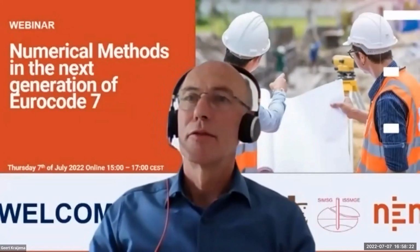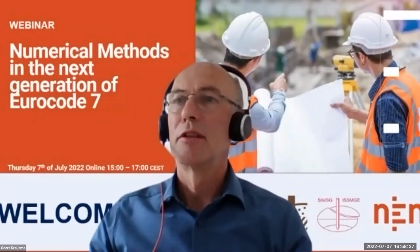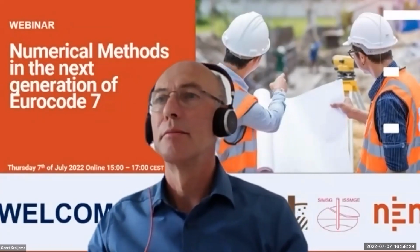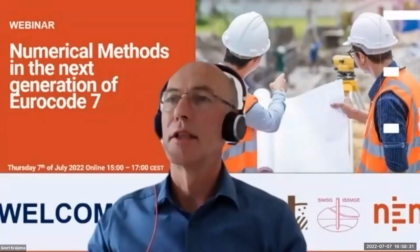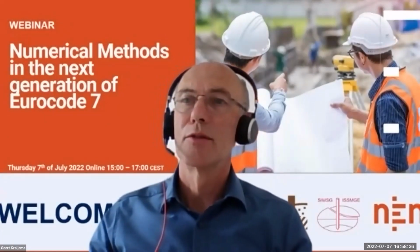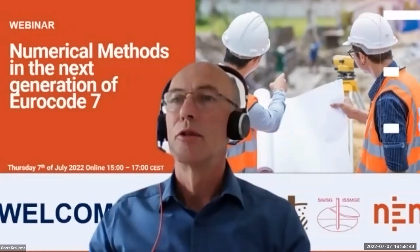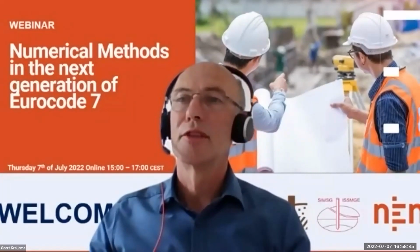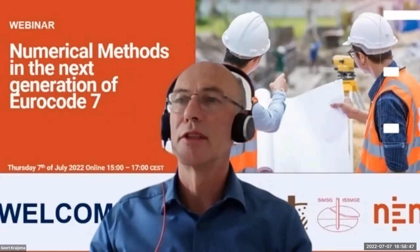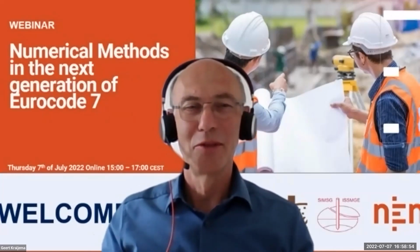So the next question is from Darius. Do you know whether the required minimum values of the reliability index beta as per EN 1990 are reached using the new numerical modeling methods? The numerical methods potentially allow lowering the model error. Therefore, perhaps the material factors could be reduced to keep the same reliability. I don't know for whom the question is, but I hope one of you can answer it.